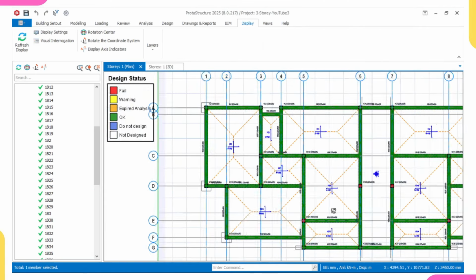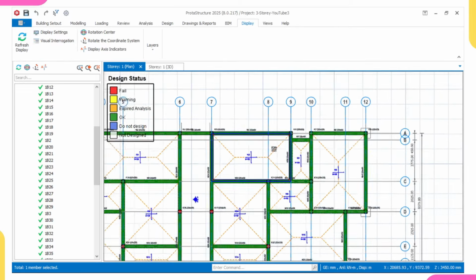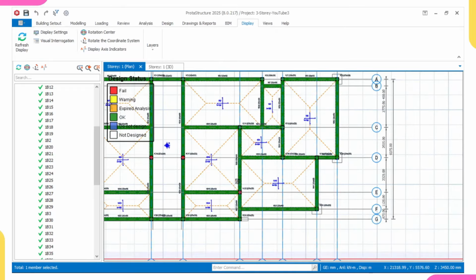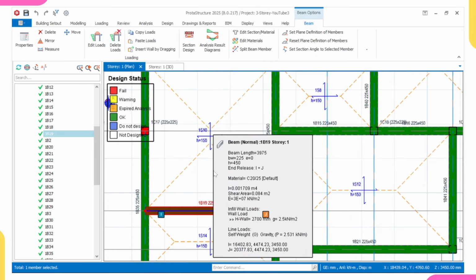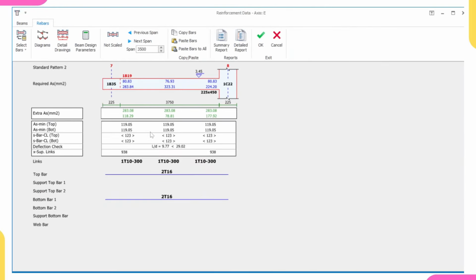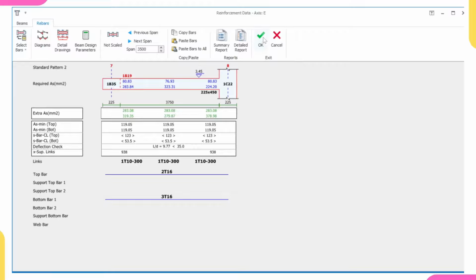So I'll just check one more beam, and then move over to Chrome so that this video will not be that lengthy. Let me check this column, let me check this beam. I'll then click on section design. So this is what I'm having, 2x16. So this is less than 100. It is less than 100. Please increase it to prevent building collapse. So I'll click on okay.